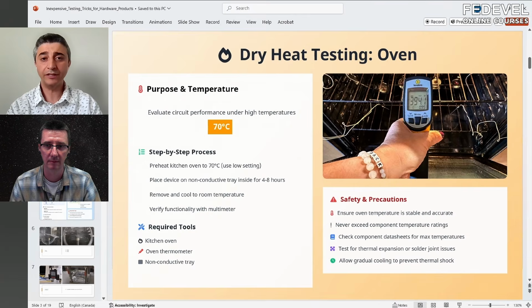So if you want to design a heat sink, you need to know what your ambient temperature is. Is it going to be 30? Is it going to be 40, 50, or even 70 degrees Celsius? Because that will impact your heat sink design, and it will impact how your processor can see it. Think about the LDOs and the buck and boost converters. All of this is critical to understand what your operating temperature is.